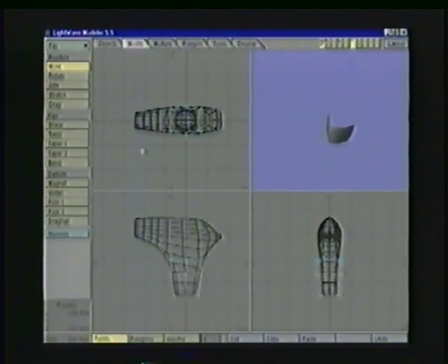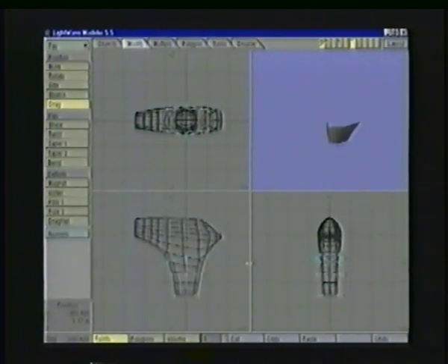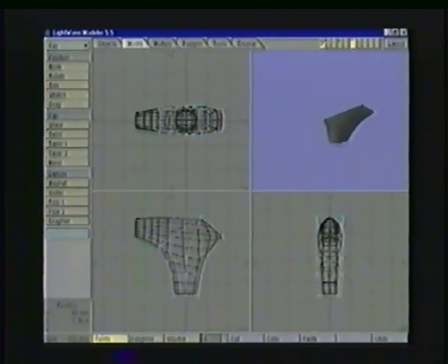Now, I can start using the drag tool to reposition these points very quickly and easily. Then I can hit F5 again. And once again, it extends it. I don't have to move them all up. I can start moving them up individually. And I'm just getting a rough estimate for now of where they should be. Now I'm going to deselect the back point here. I don't want to extend up this direction anymore. I just want to extend out this direction.